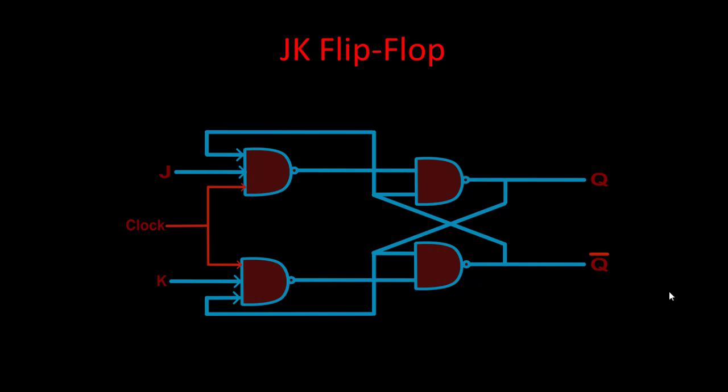With the first input as 0 0, we are applying the inputs at 0 0. It may happen that there are already some outputs. So let us assume that we have output as 0 and 1 before applying the inputs at 0 0. Now because of the strong feedback, this 0 is coming at the feedback of the lower output NAND gate, as well as the lower input NAND gate.